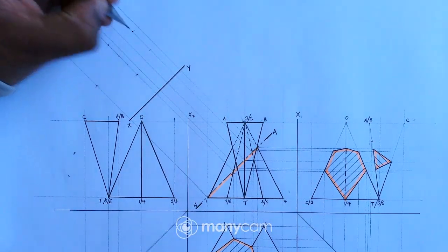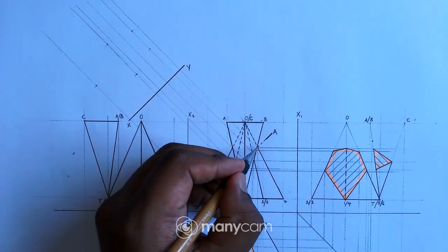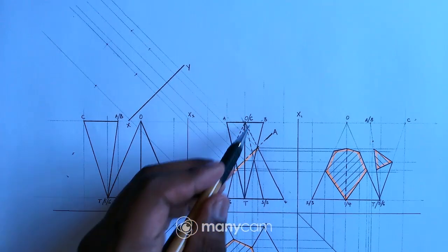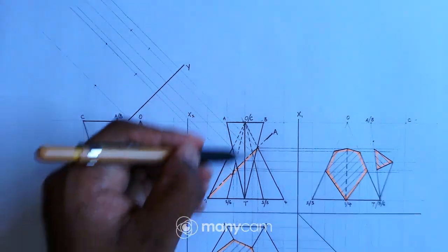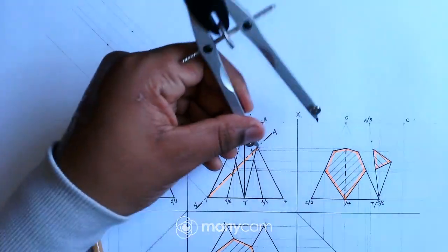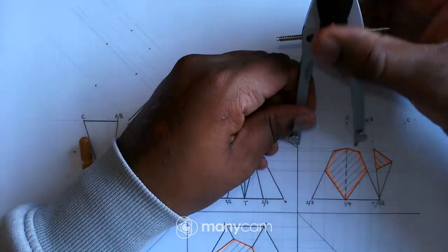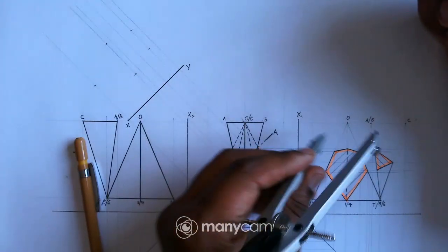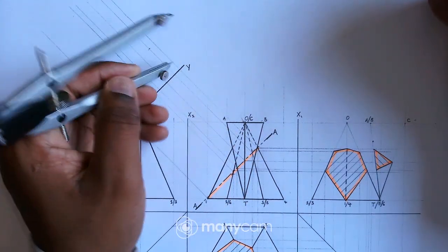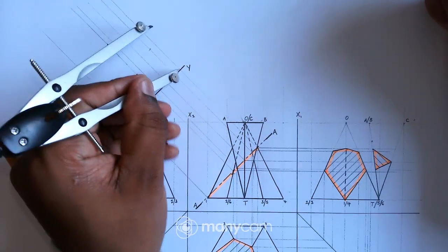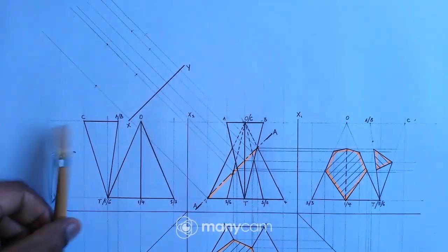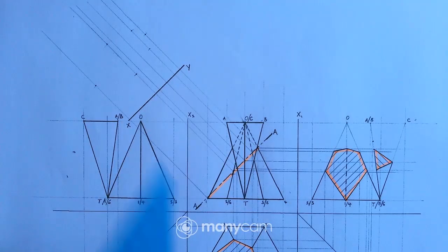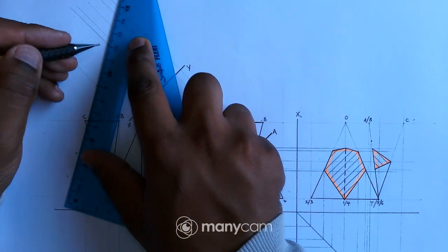Mark a point there. So I have a point there, a point there, and then the last point, it's up there. Remember, my focus is on the hexagonal pyramid, not the pyramid that's facing down, right? So the next point is this one. This is the last point. So I'll put my compass on the XY line to the point, and then now obviously I'll use this line. So I have a point up there. So this is the true shape for the hexagonal pyramid. So I can just connect the points there.